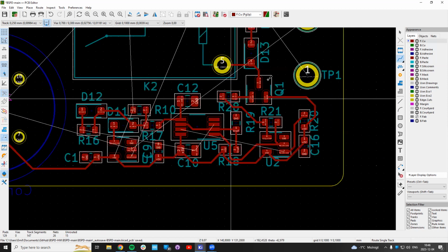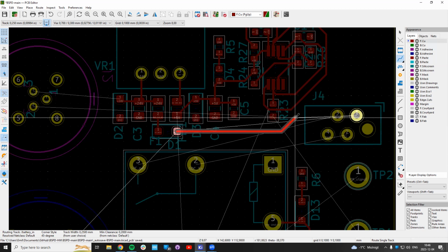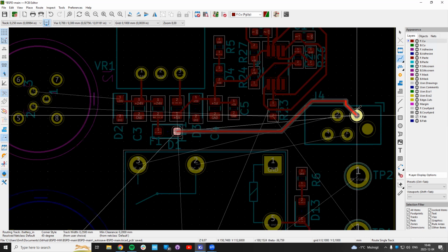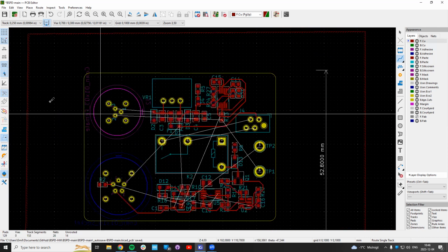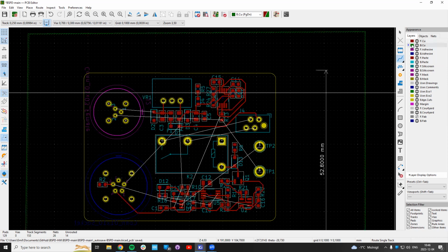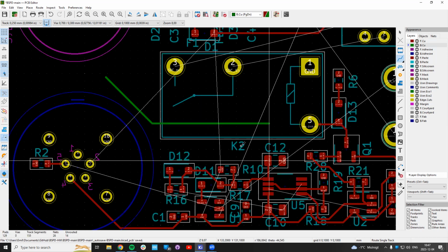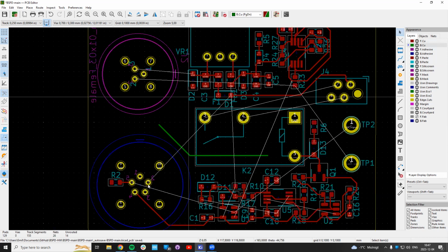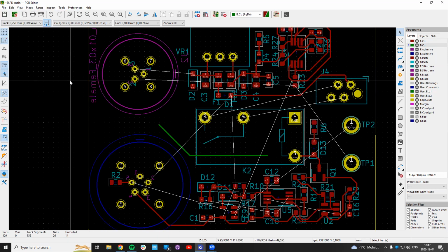So you want to always try to do as much routing as you can on the front side, not necessarily everything on the front side in the beginning, but you want to try and keep the traces on the front. This is because I can, whenever, just go to this layer or press V to hop between layers, and I can make a trace on the backside. What happens is that if I have ground here and I have some component, the current will go like this, right? And then it will have to go around this trace because the trace, I will have to build for you to see this, I think. Sorry. No, okay. Sorry.